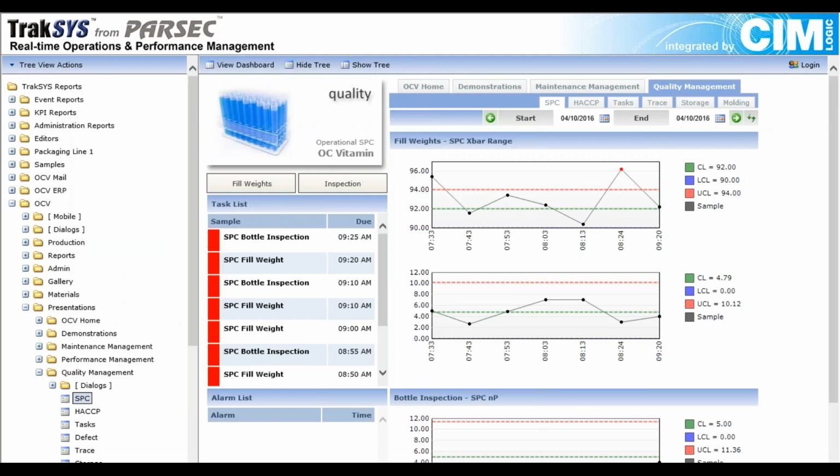Historically or typically within manufacturing processes, you might be doing quality checks on a time basis. So maybe you're doing checks every half an hour or every hour, but you also might be doing checks on a unit production basis. So maybe when we've produced every 1,000 units, we need to take 5 samples. What you may or may not have considered is that you might also want to do event-driven quality checks. So perhaps after we do a changeover on the line, or after we have a particular type of breakdown on the line, we need to enforce the first 5 to be quality checked, for example. So you need to think about what these real-time triggers are. And also, if you're doing in-line quality checking, you can be checking every single unit as it goes.